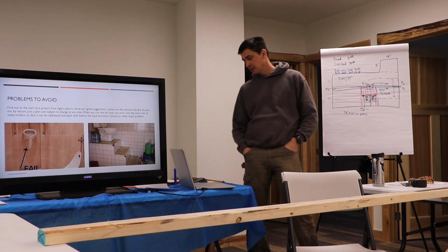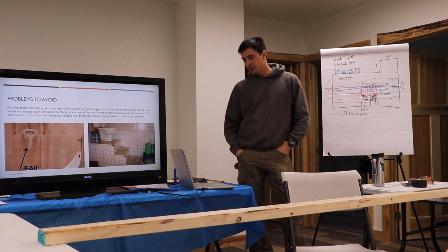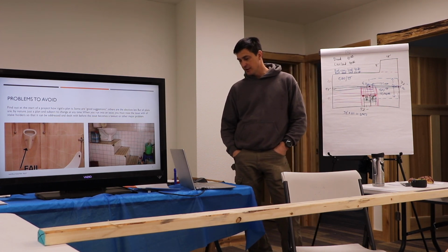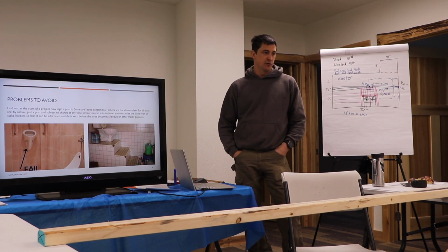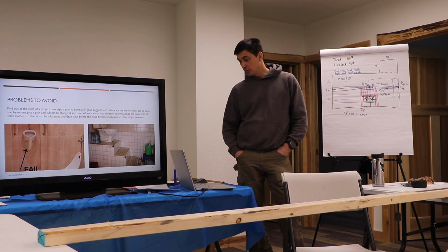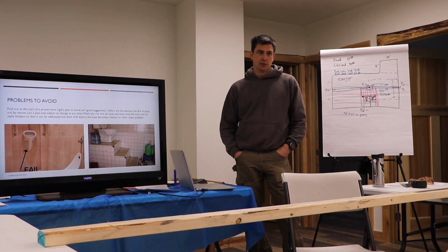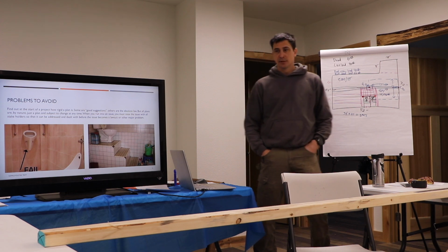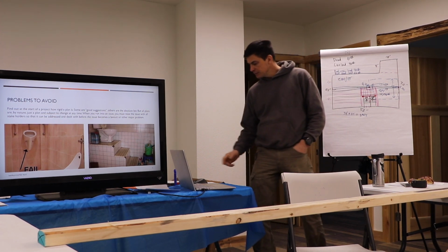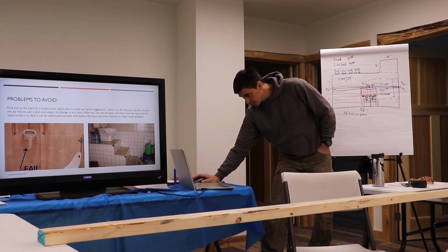And if you get familiar with the plans, then you can see any issues with them, and you can sort that out before materials are ordered wrong, or before you build something and then the homeowners walk in and they're like, oh my gosh, I didn't think it was going to be like that. Hopefully you can catch that kind of stuff if you're familiar enough with the plans.